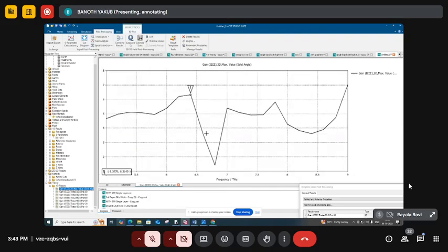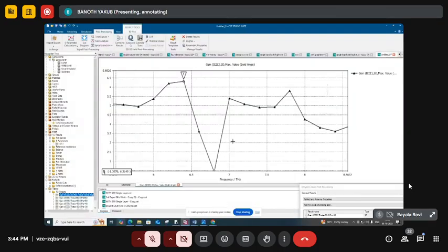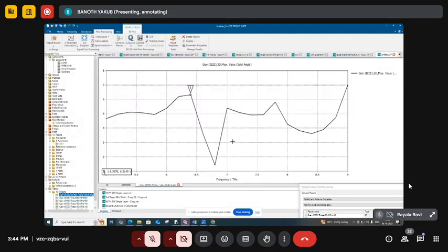So these good results came in today's hands-on session. Earlier we had only seen up to the S11 parameter. We had not seen the axial ratio values or the gain results. Now I am seeing that this design is getting good results. So now I will explain how we can get tunability in the actual output by using graphene material.